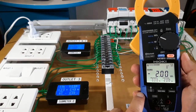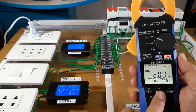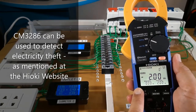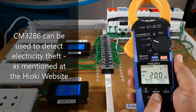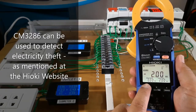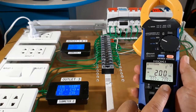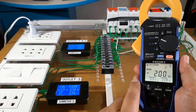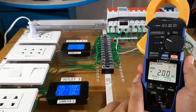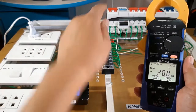And the other thing that this energy comparison function can be applied to is that, according to the Hioki website, this clamp meter can be used to detect electricity theft or energy theft. That is why the energy comparison function is significant, since if these two values are very different, for example the measured value is much higher than the expected value, then that meter is measuring much less than it should, or there is some energy that this clamp meter is measuring that does not pass through this other meter.